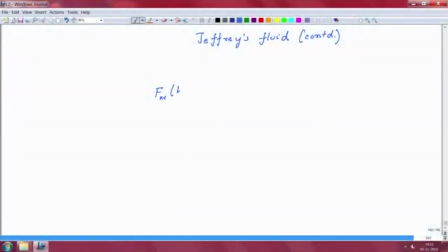So what we had done is we had written down the two expressions for the forces and then we had to simplify that. So let us just write down that one more time. We have the force for the Kelvin-Voigt body, and then the force for the spring, the dashpot, right. We have to write those two separately. So let us do that. So we have the force for the Kelvin-Voigt, and this, as we discussed, is equal to the force in the system.